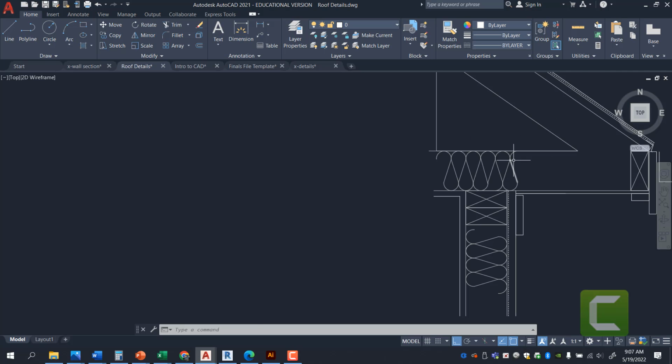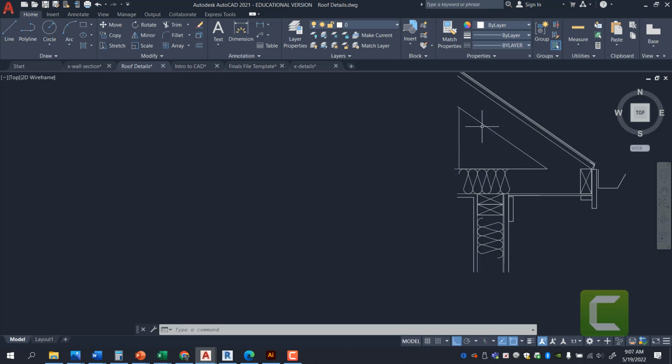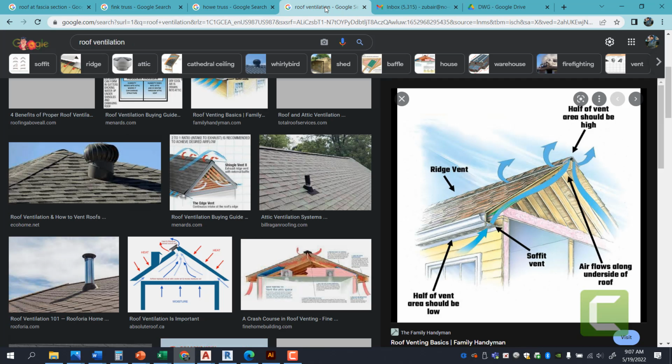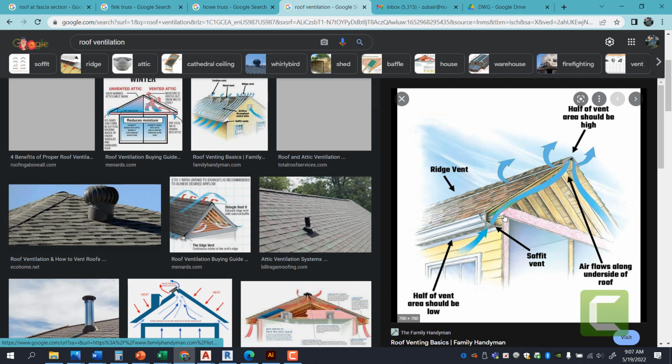And as that comes up, it's only supposed to be everywhere that you have an enclosure. So your insulation can technically end right here. As we saw in the diagram here too, as we were talking about roof ventilation, your insulation technically ends right here. This airspace is necessary for your soffits to breathe and be able to let out the hot air in